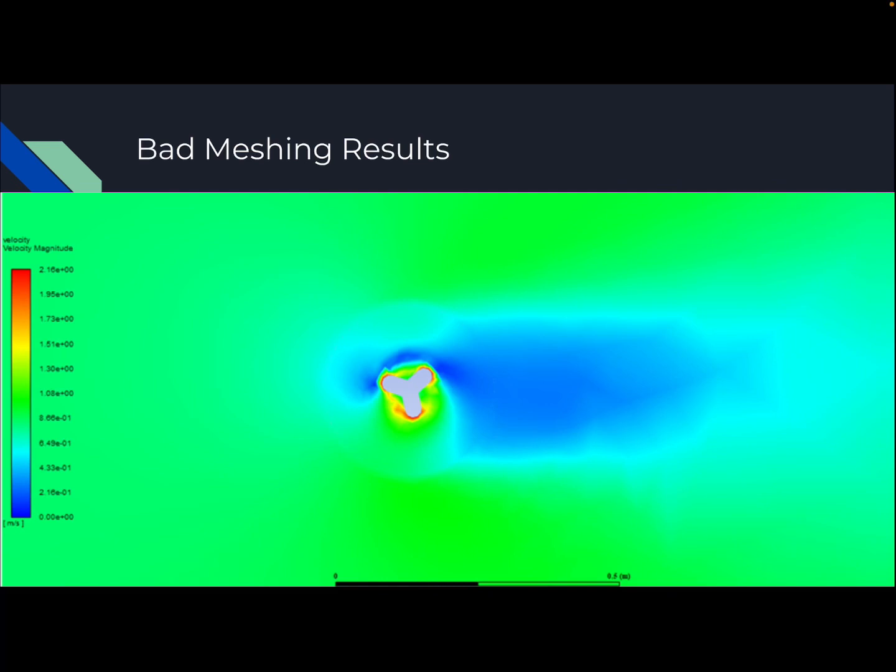That's actually the 0.3 meter circle that we put in our geometry earlier that rotates, that gives the inference that our fidget spinner is rotating. Because our mesh isn't very fine right there, it actually changes and shows the velocity being different there, versus having a better mesh. You'll see that there won't be that visible blue circle around the fidget spinner.